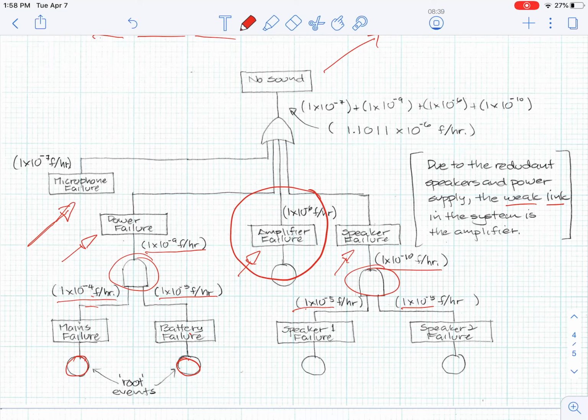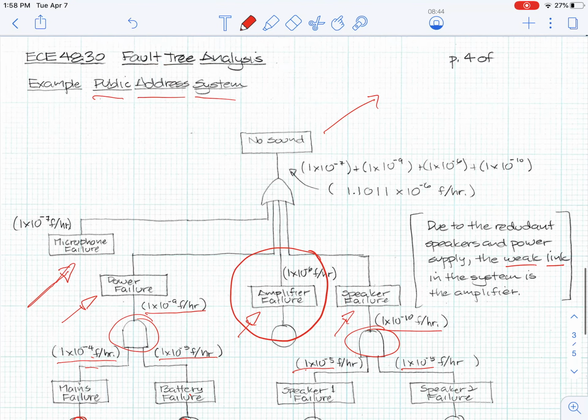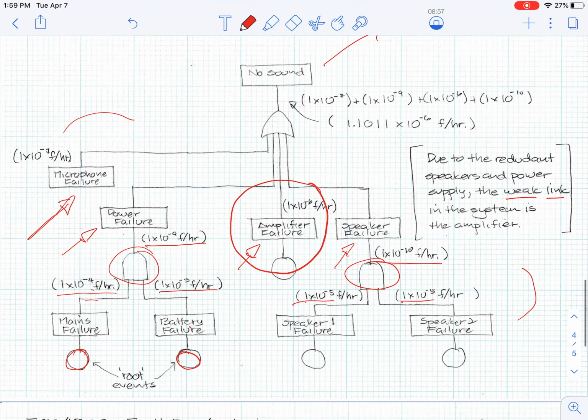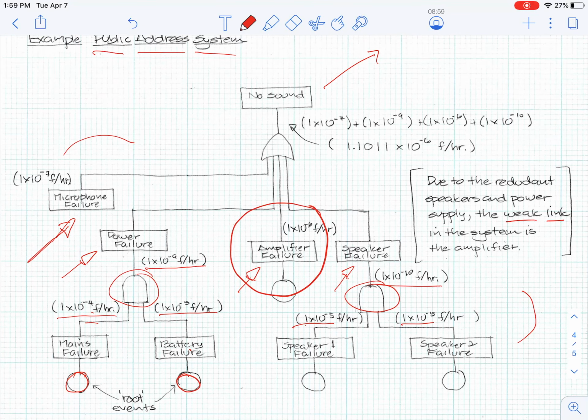This is just a basic fault tree analysis. What I'm trying to do is look for something that I want to happen rarely in the system, determine all the causes that can make that fault occur, and then add what redundancy I can to the system to improve that. This is used in airplane design and aerospace all the time, and it's a very useful thing.